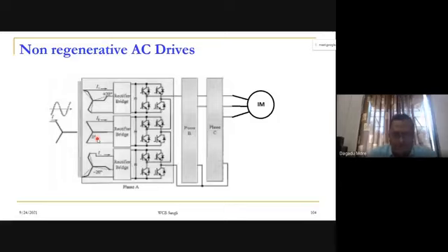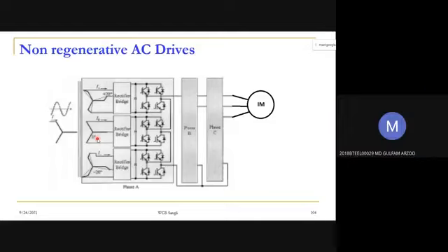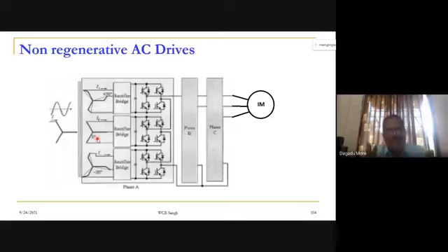You see that we are having one primary winding, and how many secondary windings? 9 secondary windings. Imagine the complexity involved in that. We are having a 3-phase transformer with only one primary winding, star connected, and 9 secondary windings.